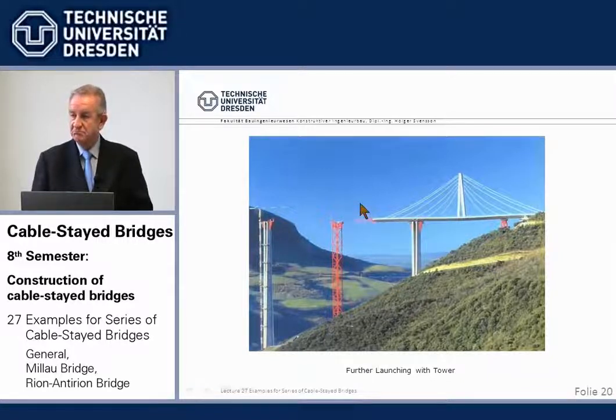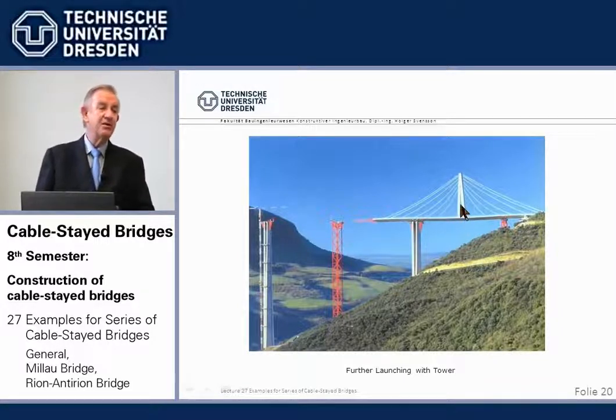Well, it has been done before. We've done it for incrementally launched concrete bridges. It is rather tricky, because to cater for this load, when you transfer the load from here to there, it's not so nice. But apparently, you could do that without additional supports. The towers were shortened, not the usual 90-meter towers, but only 70 meters, because the wind on the 90-meter high towers would have been too much. So in order to reduce the wind, that was lowered.